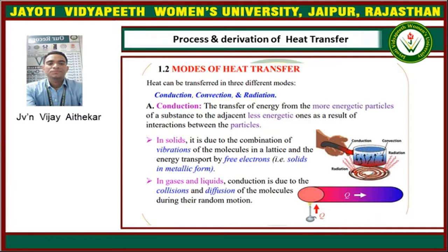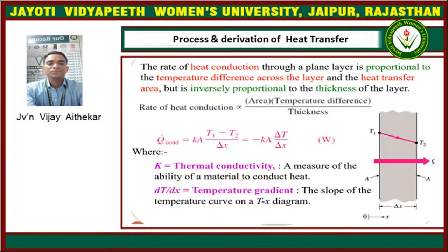First is conduction, the transfer of energy from the more energetic particles of a substance to the less energetic ones as a result of interaction between the particles in the solid. It is due to a combination of vibration of molecules in the lattice and energy transported by free electrons. In gases and liquids, conduction is due to collision and diffusion of molecules during their random motion.